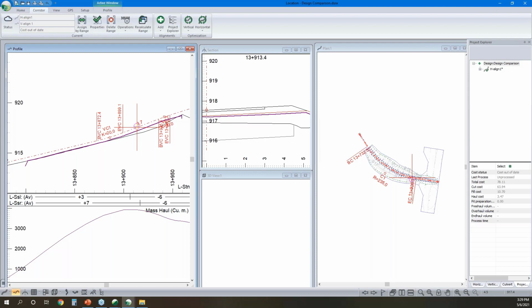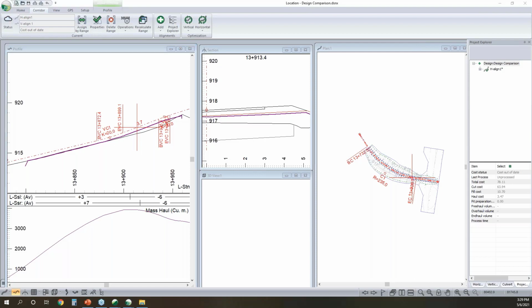So I see we do have a bunch of questions here now. I guess let's start from the top. There's a question related to LiDAR points. One of the reasons I thinned my LiDAR data down on import is the bigger the data set, the slower things get. So we recommend folks try and keep their data set to be under 10 million points. If you focus in on what you need, you're going to have faster computing time.